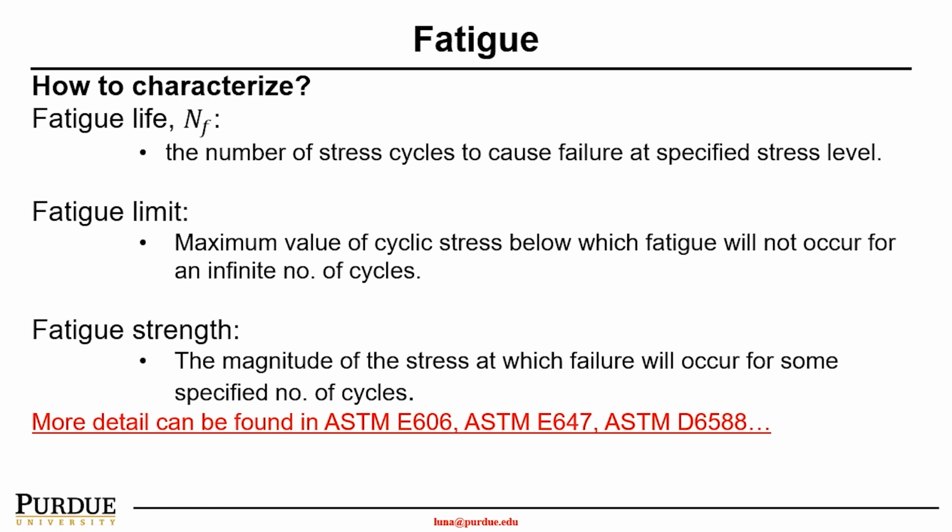And fatigue stress is the magnitude or amplitude of the stress, right, at which failure will occur for a specific number of cycles. For instance, you could have 10^6 cycles in this case, and then your fatigue stress is 200 megapascal, something like that.